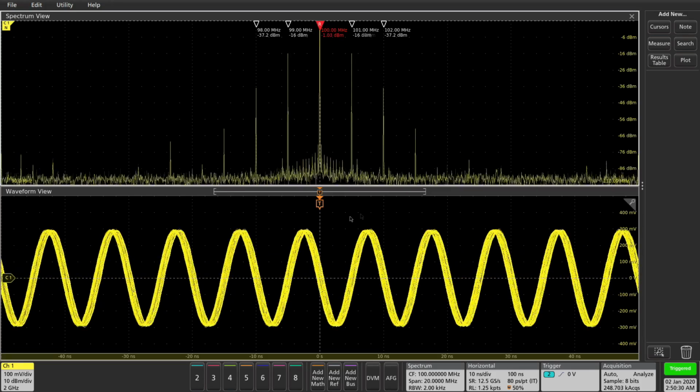Now this phase modulation is also 1 MHz and at 20 degrees, and you can clearly see now we have a zero crossing that is blurred out because every time the signal is captured there is high persistence here. You can see it traveling back and forth by about 10 degrees. In the spectrum domain you can see now the Bessel functions very clearly.